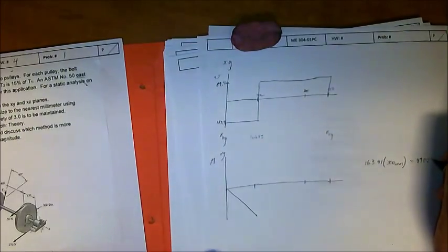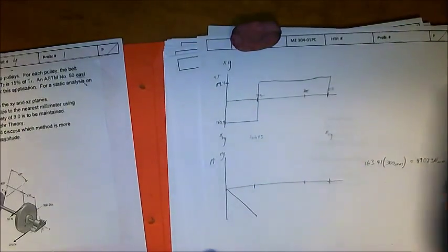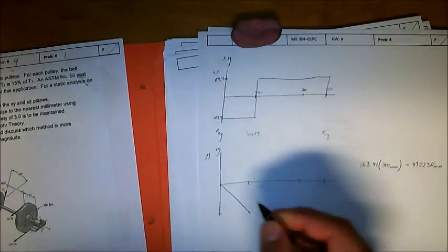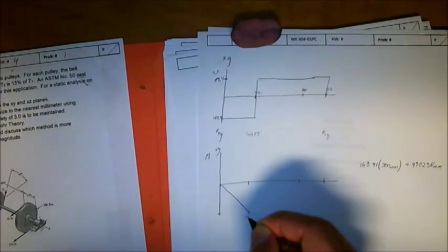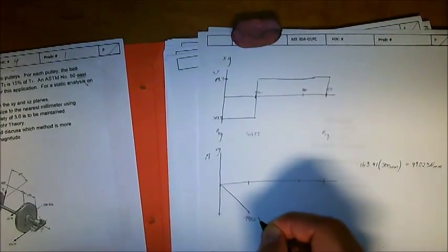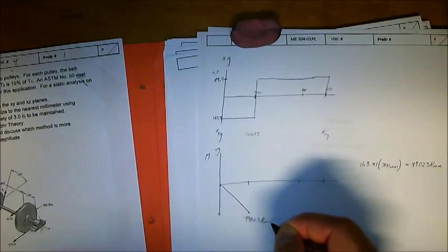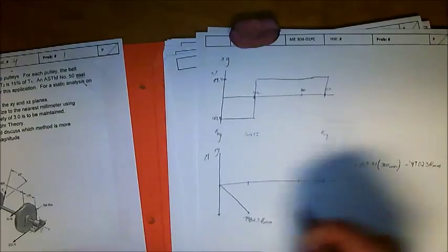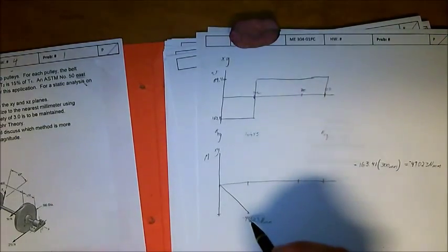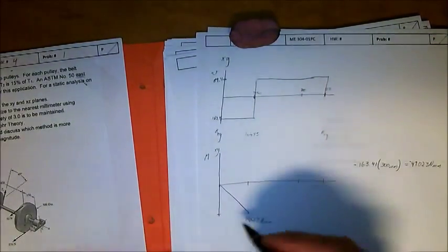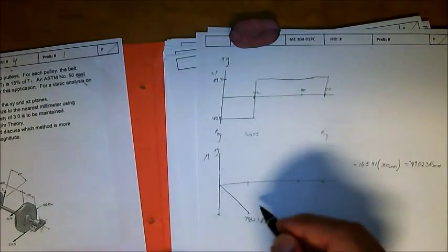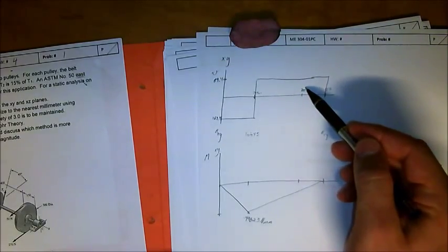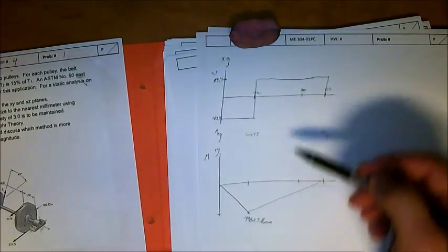Cool. Alright, so we have this down here at negative 49,023 Newton millimeters. And actually, if I had done this, this is actually negative 163, so negative right there. So you know it's a negative slope, and you end up with a negative moment, so great. And then again, since you know it has to go to 0, you can just draw a straight line across from here. And you also know that this is all a positive slope, or positive value, so it's going to be a positive slope down here. And we're good, and you can make that assumption. And if you want to check, fine, but we already did the sum of the force equation.